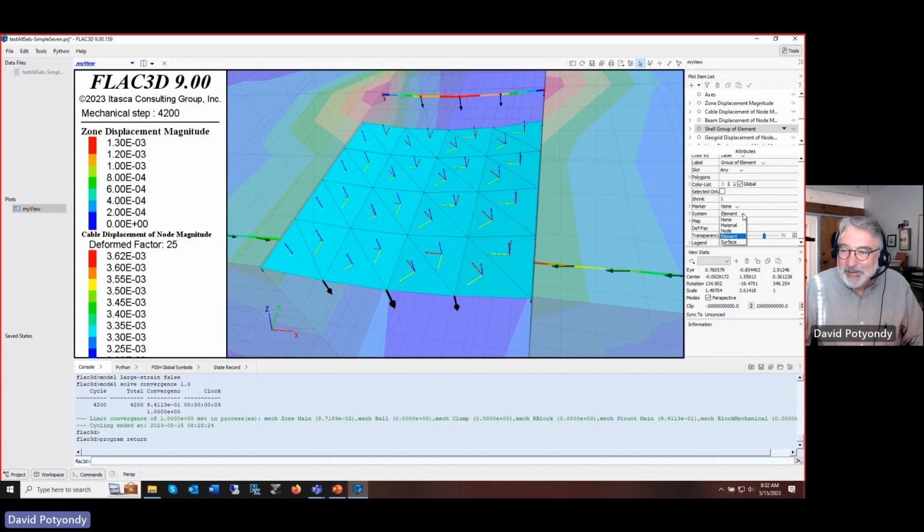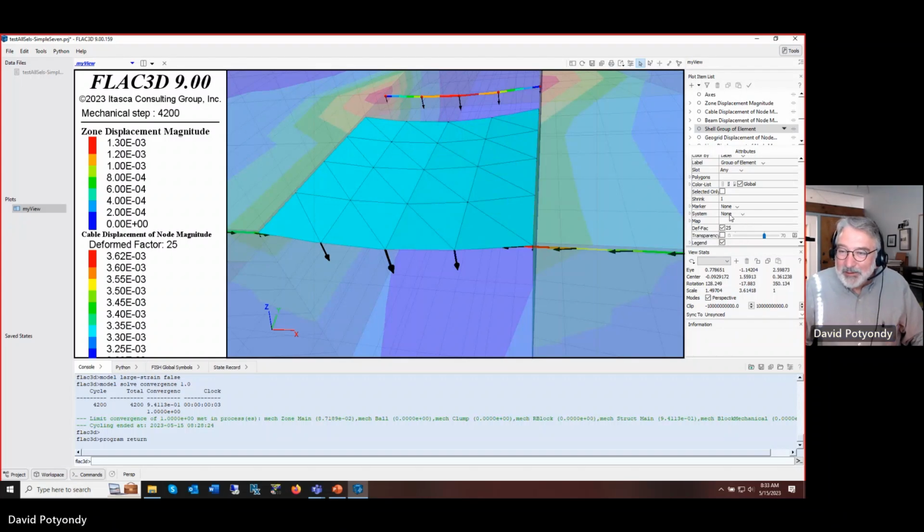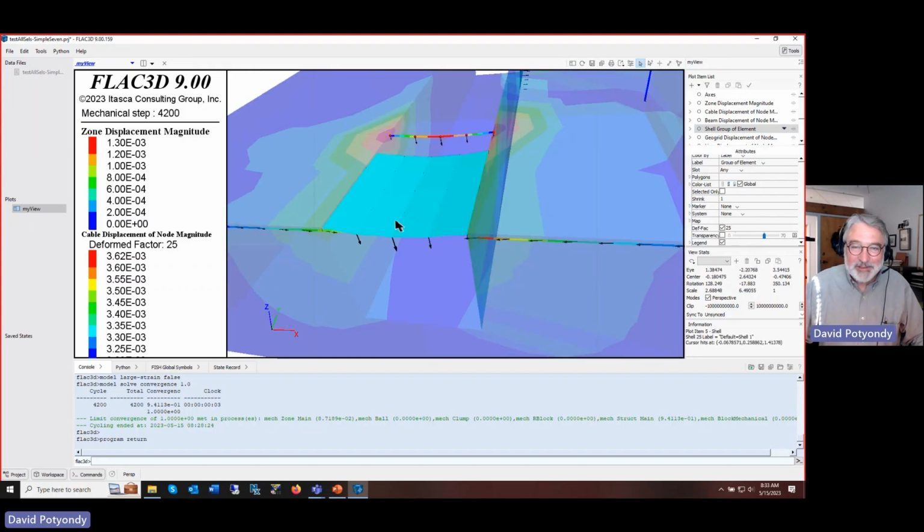There's also a material system. If you use an orthotropic or anisotropic elastic body, you have to specify the principal directions of the material, the principal directions of orthotropy. So you could look at that system as well if you had that. And then there's something called a surface system, which is going to be used when we recover stress resultants or stresses on shells. Okay. And we'll get to that a little bit later. There's also, yeah, let's just leave it at that for now.